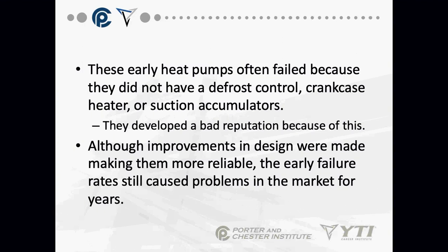There were no crankcase heaters, and there were no suction accumulators. Remember, I showed you the diagram when we were doing the EPA of a suction accumulator. The suction accumulator is a tank that's designed not to send liquid refrigerant back to the compressor. Although improvements in designs made them more reliable, the early failure rate still caused problems in the market for years. People wouldn't install them because everyone said heat pumps sucked. There was a reputation that they're not working properly.